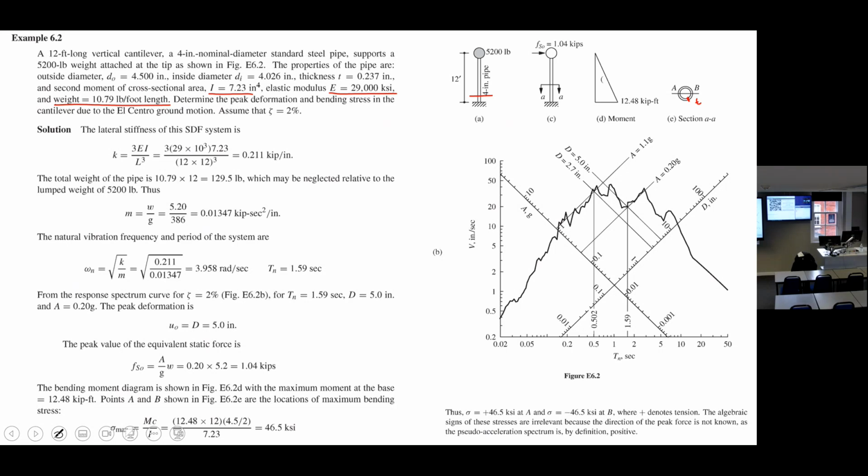this is a good representative of elevated water tanks. We had some examples in this module, elevated water tanks as well. I'm not sure, but this is a really good example, and it's common practice in the UK, if you noticed. Elevated water tanks usually have concrete columns, not steel usually, and a very big water tank at the top, right? Just to supply the water pressure for the residents around the region. So this is a very good example of those kinds of structures.